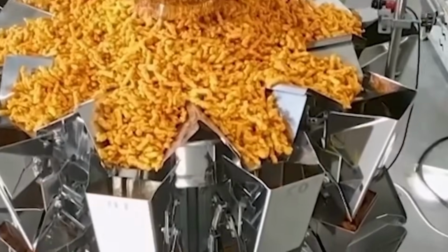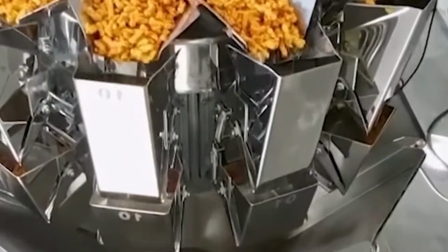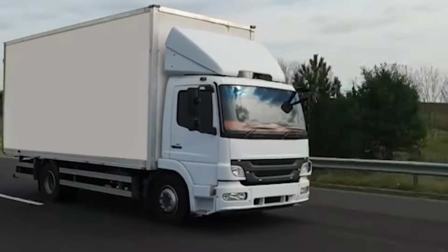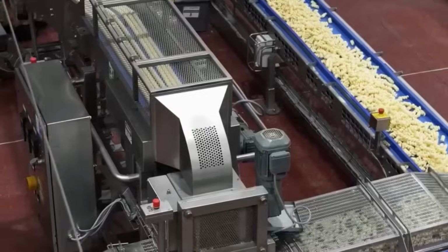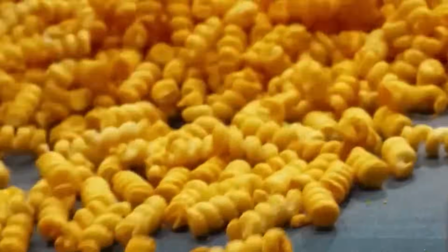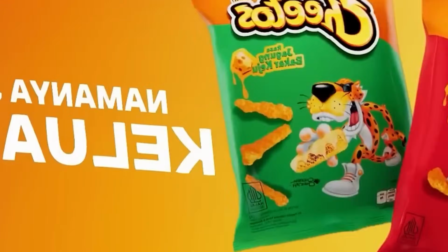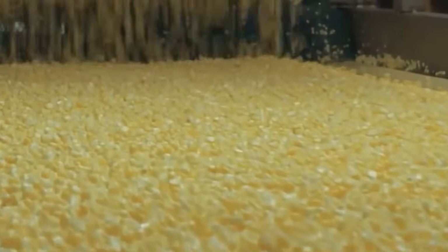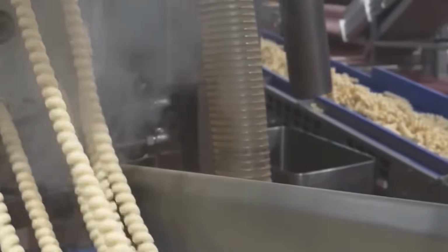The chamber uses dual shaft paddles rotating at independent speeds to ensure homogeneous hydration without introducing air pockets. Live steam is injected directly through precision steam valves, with real-time moisture levels monitored using NIR, near-infrared, sensors and inline conductivity probes. From the preconditioner, the moistened meal is transferred directly into the barrel of the extruder.